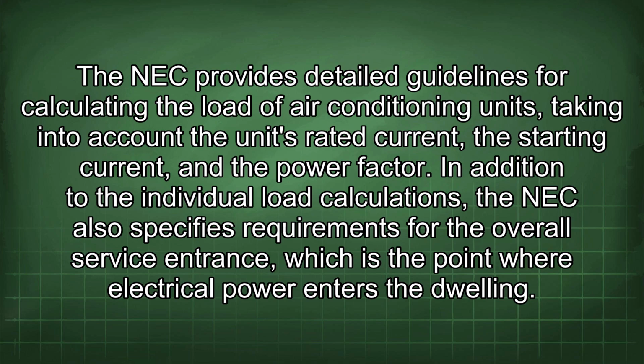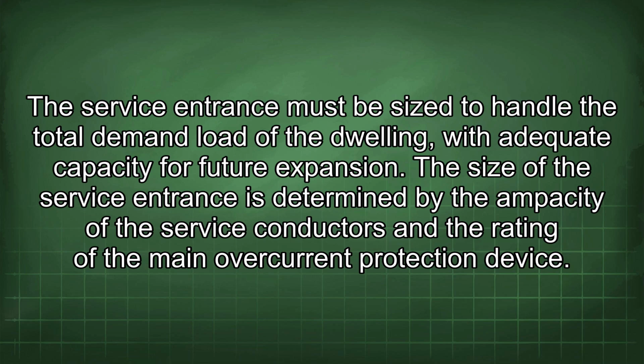In addition to the individual load calculations, the NEC also specifies requirements for the overall service entrance, which is the point where electrical power enters the dwelling. The service entrance must be sized to handle the total demand load of the dwelling, with adequate capacity for future expansion. The size of the service entrance is determined by the ampacity of the service conductors and the rating of the main overcurrent protection device.